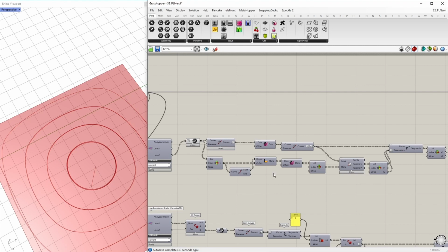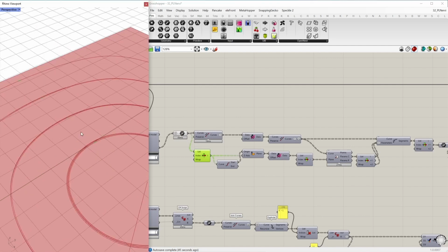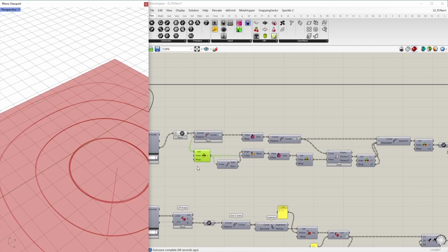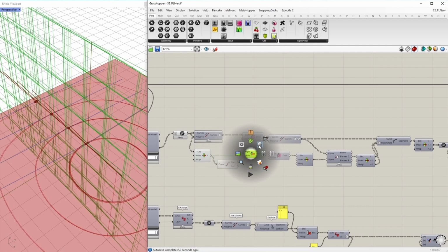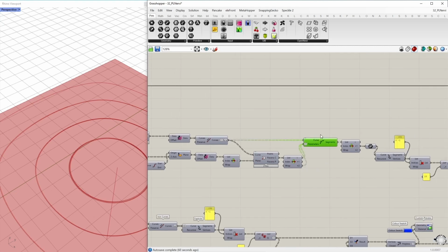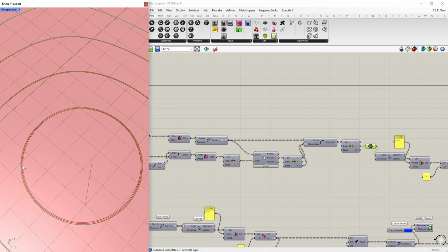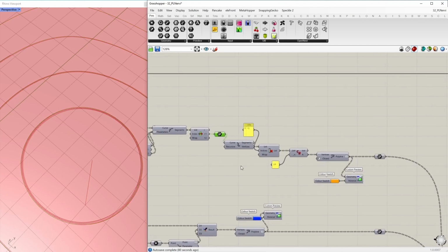To get rid of the multiple circles here, we use the first segment of each of these curves at the start point, and we create a perpendicular plane to the first segment, and then we intersect the segment with the single lines, and with that we can later split the segments into just the section we want from the curve, which is going from this point one full rotation around and back there. And then we have to rebuild this curve.